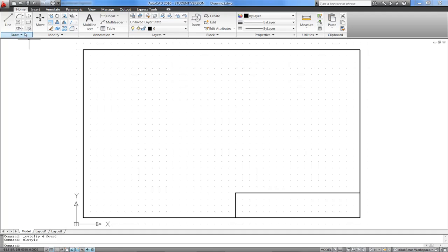Rather than using the line tool to define the basic shape of the floor plan, what we're going to do is use the multi-line tool, which will allow us to create a specific line type for the external walls and a different specific line type for the internal walls. The simplest way to bring up the multi-line tool is to type ML and hit enter, and you'll find that when you click to start the multi-line and pull away, by default you get a double line 20mm spaced, but